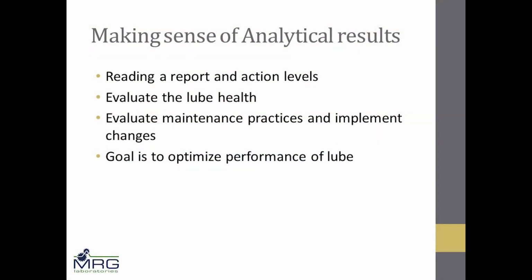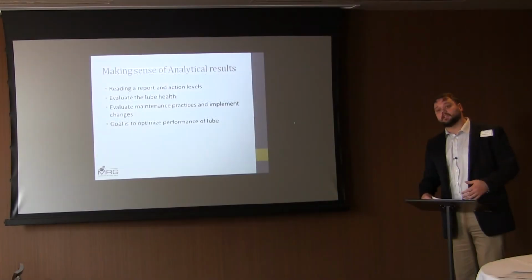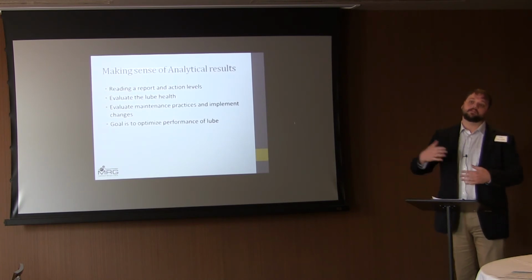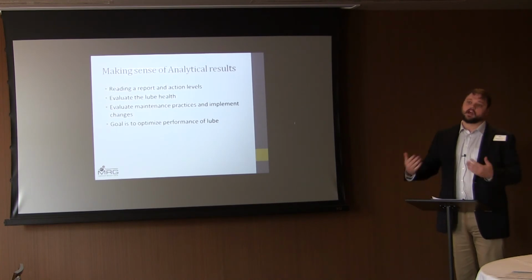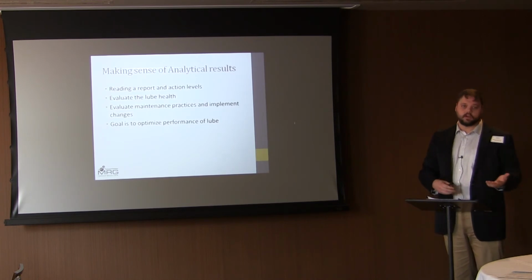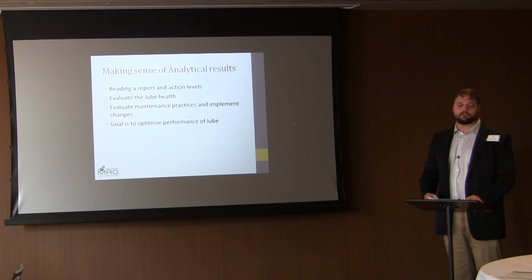And then also it can help evaluate your maintenance practices and implement changes. So say you're testing your grease, and every time it comes back the grease consistency is great, antioxidant levels are good, and everything looks okay, then maybe you can decrease your lubrication frequency because your grease isn't getting pushed to the end of life, so you aren't optimizing that life of the grease. You could be saving money and not greasing as often. It's things like that we can work with the customer on and try to maximize the potential they're getting from their lubricants. Like I said, the goal is to optimize the performance of the lubricant, whatever it's doing, whether it be draw fluid or fluid that's helping run motors, hydraulic pumps, anything like that.